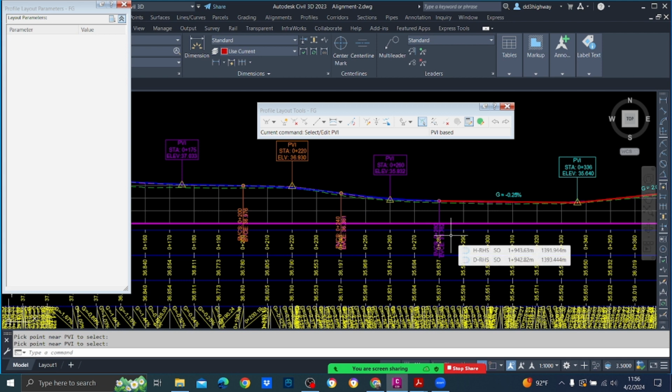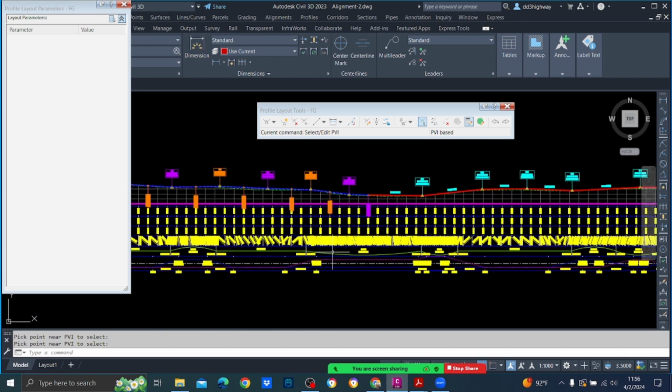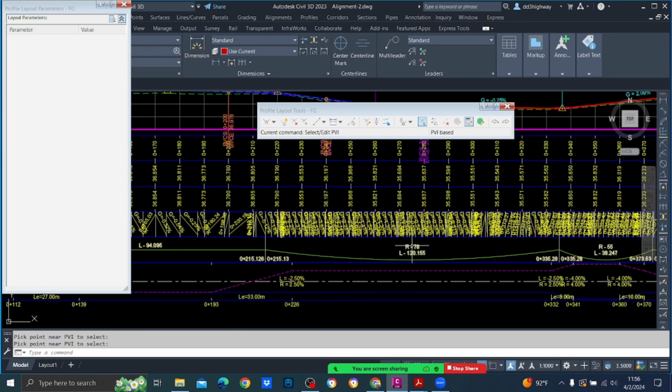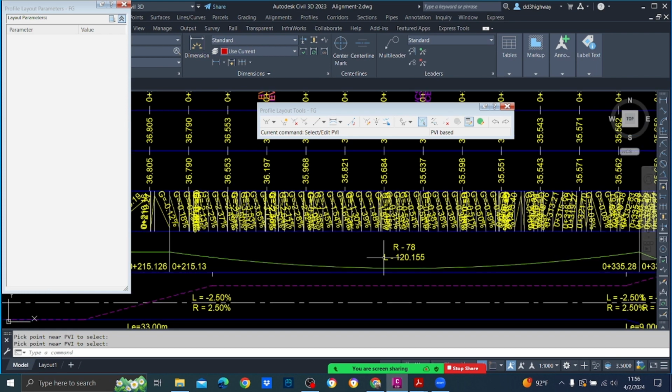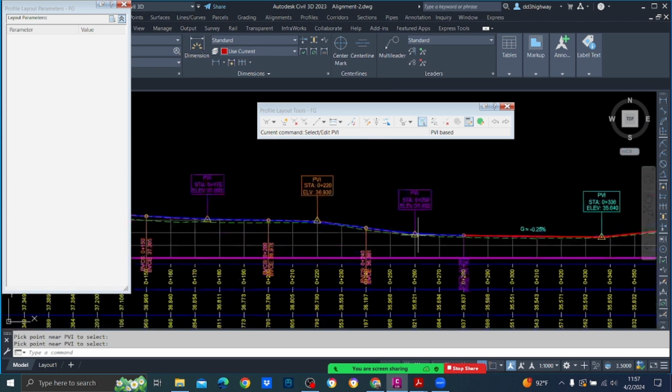Now how is this? No filling at all. How did we manage to do this? Because we considered this region as 40 kmph. This was possible because the horizontal curve was going for 40 kmph, not for 50. Because in such a case, if you provided 50 kmph design speed for the vertical curve with heavy filling, it is not going to be worthwhile. Right, then the next thing.